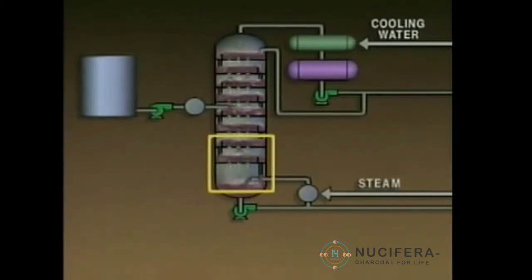If the temperature at the bottom of the tower is too low, less of the lighter components will vaporize and move up the tower. Another place where temperature control is important is at the feed point. The temperature at the feed point should be within the boiling range of the mixture. The temperature at the feed point should be close to the temperature of the feed tray. The temperature of the feed tray depends on its physical location in the tower. For example, the lower the feed tray is in the tower, the higher its temperature will be.